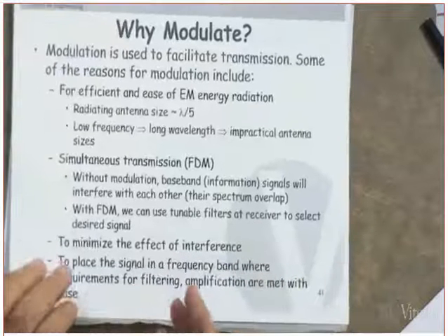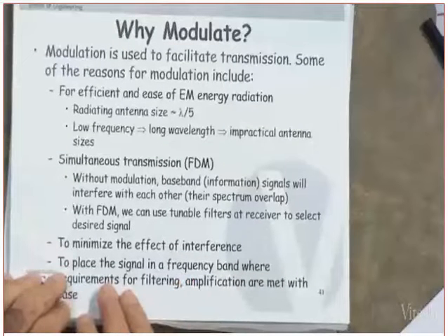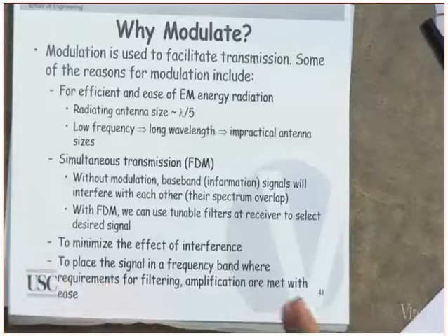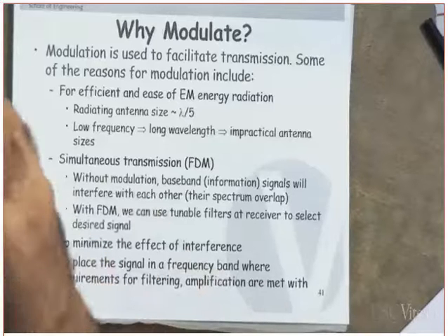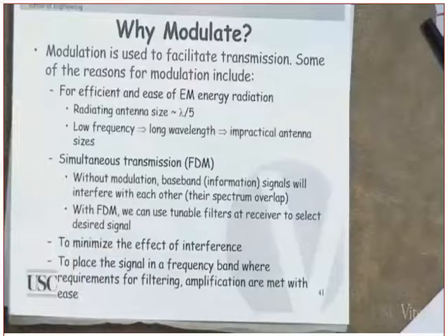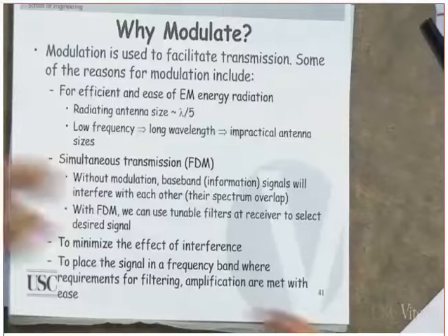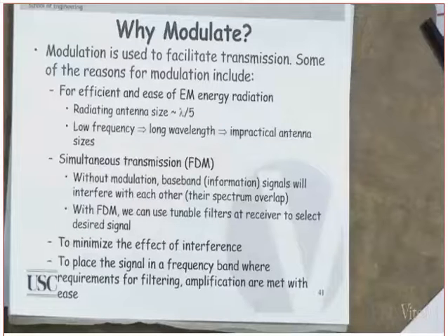Now, some other important function of modulation is that sometimes interferences are more concentrated in a certain band than others. Are you following me or not? If you look at the spectrum of coaxial cable, for example, you will see that it starts from roughly 5 megahertz. You might say, how come it does not start below that? Starting below that, there will be interferences from electrical or mechanical systems operating in the vicinity. Are you following that? Or some amateur radios, ham radios operating in the vicinity. Some bands are more noisy than others.